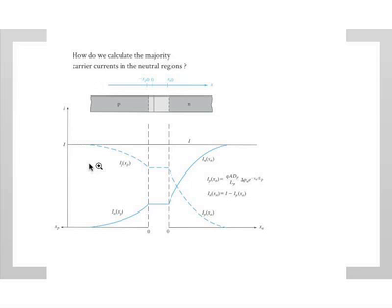So this is plotting current as a function of position across this PN junction. Remember what I said, the total current across the PN junction is exactly the same. So if I plot the total current, it should be a straight line. Indeed it is. Now let's look at what creates this total current. In the junction, or near the junction, we already know it's mostly the diffusion current. We just calculated that.